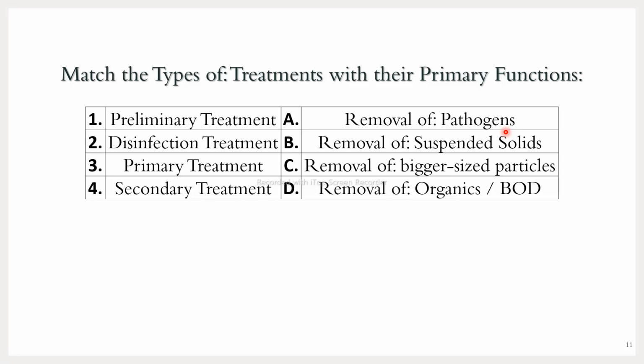Another way of removing pathogen is ozone treatment. Ozone has a shorter lifespan inside water than chlorine, but ozone is a more effective way of removing the pathogen. In countries like Finland, Norway, Sweden, etc., the northern European countries, or the cold countries, and also where the population is not much, where the water supply can be limited within a smaller region than the cities of India, there the ozone treatment is more suitable. But the presence of ozone in water is even more harmful than the presence of chlorine during your consumption. But it has a shorter lifespan, so it is suitable where the pipeline length is not very high.